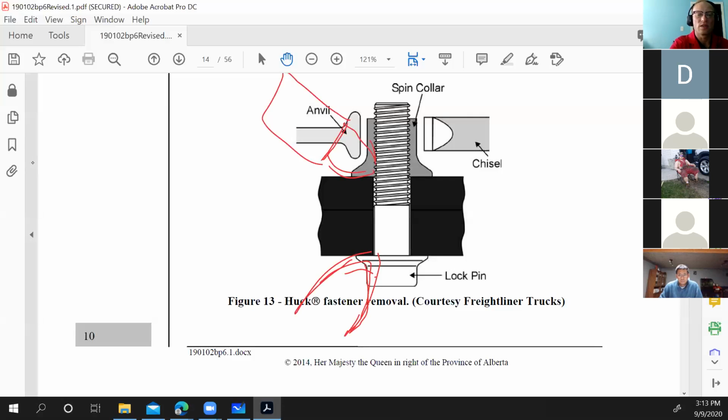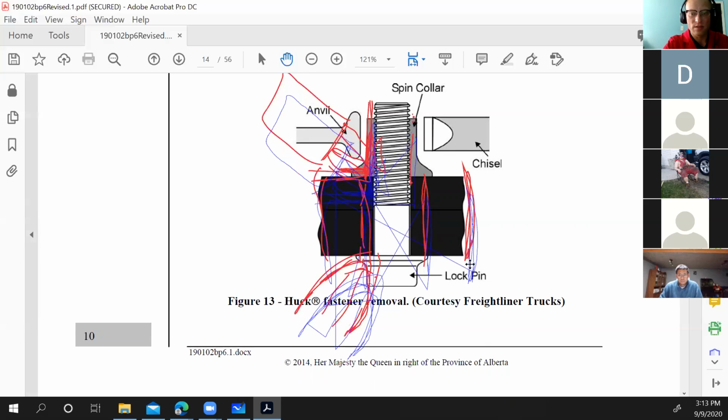With what we've talked about, could you see how this might be a problem? Oh yeah. Fire. Now, do we still do it? Yes, people do it every day. Are you damaging this frame? Well, it depends how good you are with the torch. I was just going to say that. Depends how good you are. So, exactly. If you have to spend 5 minutes heating around here before you blast this with oxygen and blow that collar away, you have definitely heated up all around here and probably made some problems.